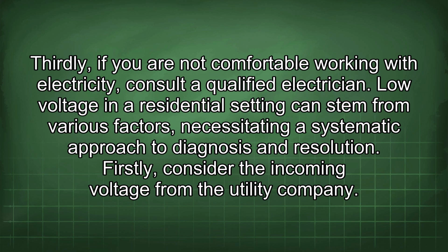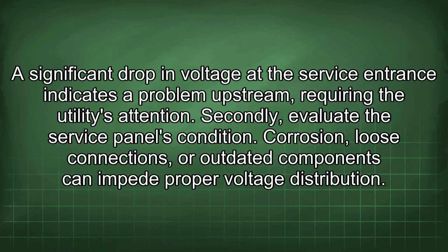Low voltage in a residential setting can stem from various factors, necessitating a systematic approach to diagnosis and resolution. Firstly, consider the incoming voltage from the utility company. A significant drop in voltage at the service entrance indicates a problem upstream requiring the utility's attention.